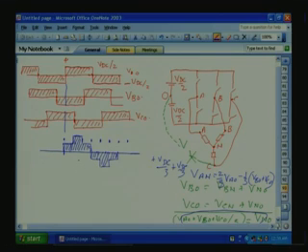If you do the Fourier series of this one, this will not contain triplen order. That means this will contain fundamental, 5th, 11th, 13th, all harmonics only. 3rd, 9th, all these harmonics will be absent. All this triplen order will be across this VNO.